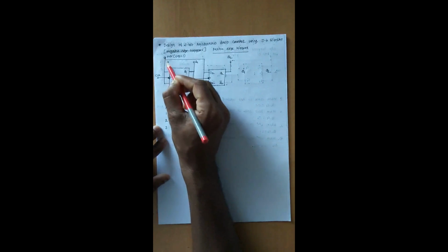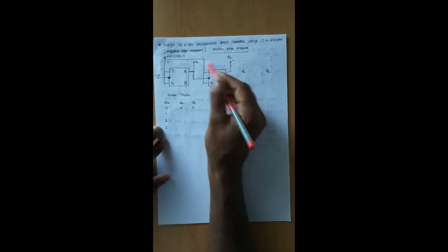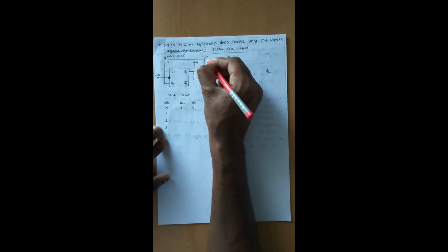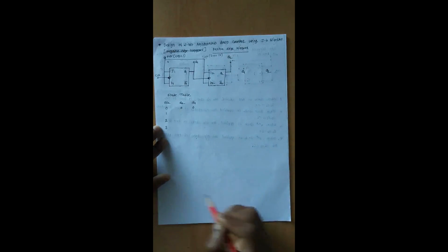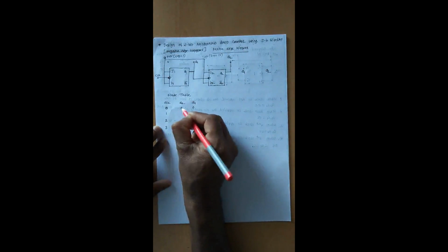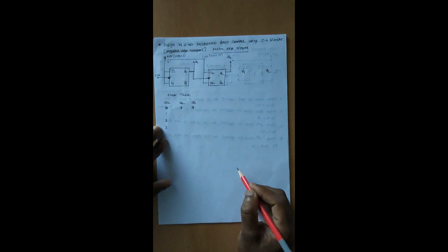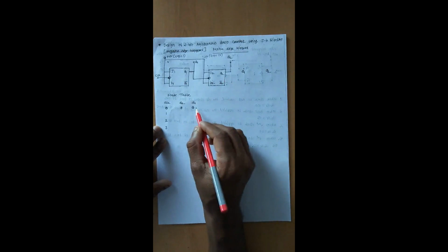Okay, because both the flip-flops should be in the toggling condition, J1 K1 and J2 K2 are connected to plus 5 volt, which is nothing but logic 1 value. For the initial condition, we assume that no clock pulses are applied. Hence Q1 and Q2 are both 0 0.